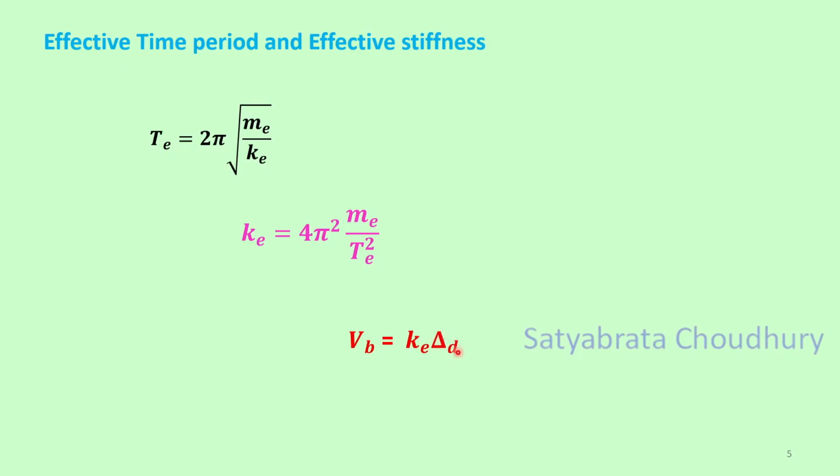In the design displacement we have considered the design drift. In direct displacement based design, as we saw in the last video, only drift can be accommodated, only a single parameter. So that is accommodated in the delta D. Further, the nonlinearity of the system is accommodated in the KE, the effective stiffness.